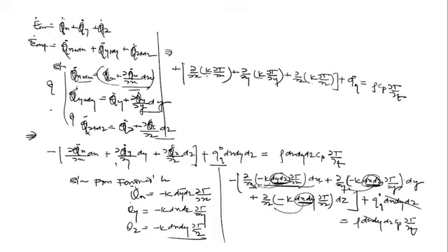If k is a function of temperature, then obviously k is also a function of x. Because in general, k is a function of temperature, and temperature is a function of x, then indirectly k is a function of x. No, I have already assumed kx, ky, kz are the same. But what I'm talking about is that k may be a function of temperature, yes or no?